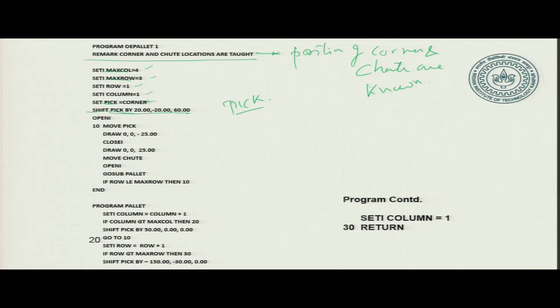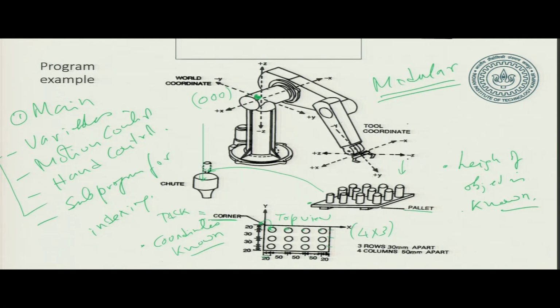Next what we do is we open I. Open I means open immediate. So, this is a closed loop command. After the gripper is opened with open I, what we do is move to the point pick, okay. Then it goes to point pick, and this is the point pick, okay. So, this is my point pick now. So, it goes to the top somewhere here. So, that is my point pick, okay. In this view it will position somewhere here, my gripper is somewhere here now, okay. Let me draw it like this. So, just on top of the object my gripper is positioned like this now, and this is my pick point, okay. So, that is my pick point now.